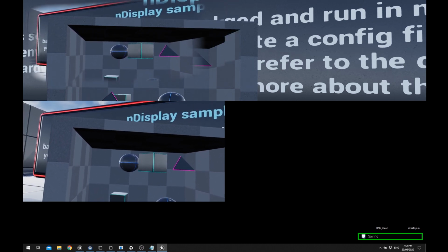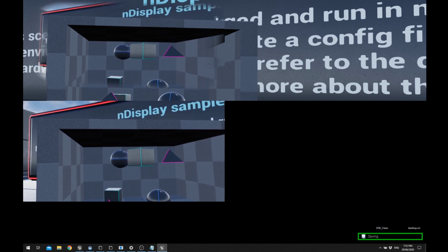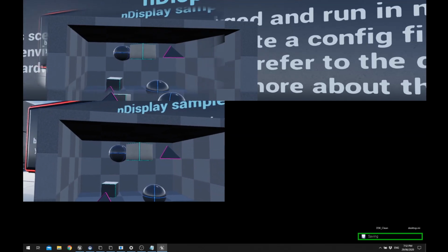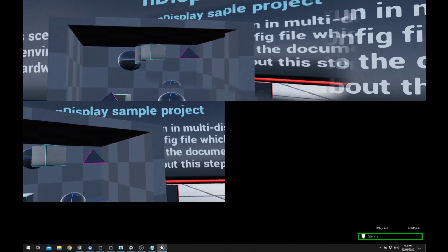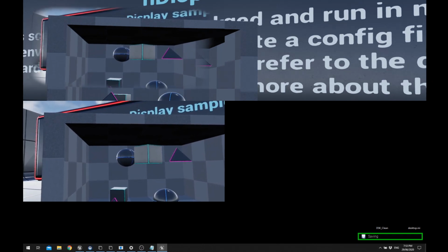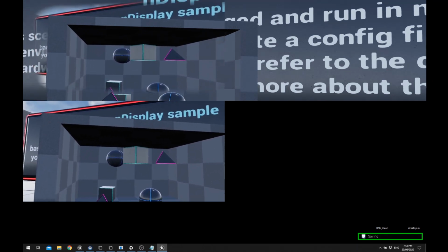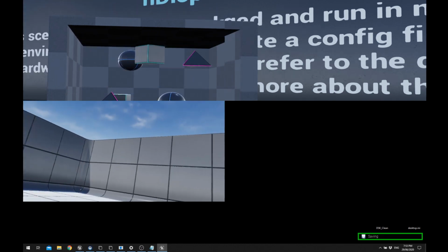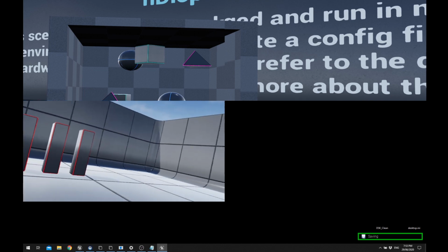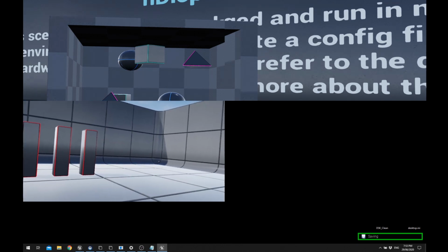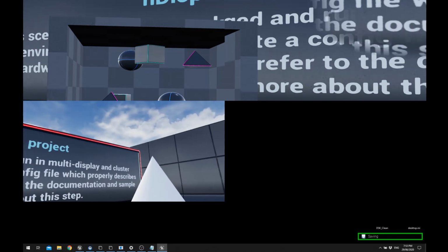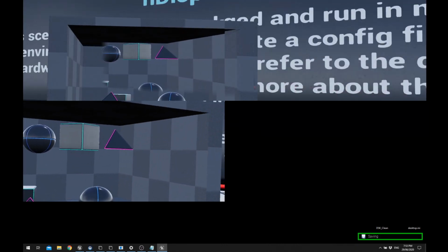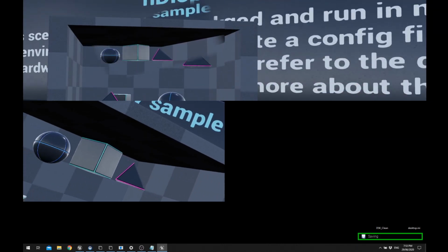In Vitali's example, he's pretty much pushing the projection render to texture that I have in the bottom left. He's pushing that off screen so you just don't see it because he's taking up the whole canvas with the actual views. But that is a really good way to debug if you're actually getting stuff right, because sometimes you might have a room config error and you might actually have a projection working, but it's pointing off somewhere well away from your stage. You can see I'm pointing completely the opposite direction and nothing is updating on my walls because that camera is just not casting out that wall. And if I spin it completely back around, the projection comes back in, and I can change my field of view down and you can see that updating within there.